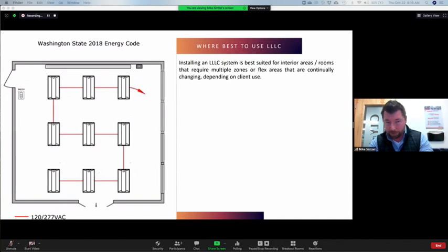It's a tricky thing with those windows along the right-hand side and multiple zones. And the whiteboard's going to need its own zone. So the front one's dimmed down when they hit that touch screen and the teacher, he or she, wants to present something. So you don't want those lights above the screen to be on. So there's multiple zones, multiple scene controls here that are possible. And then we also have to worry about emergency as well, because that's going to be another zone also.